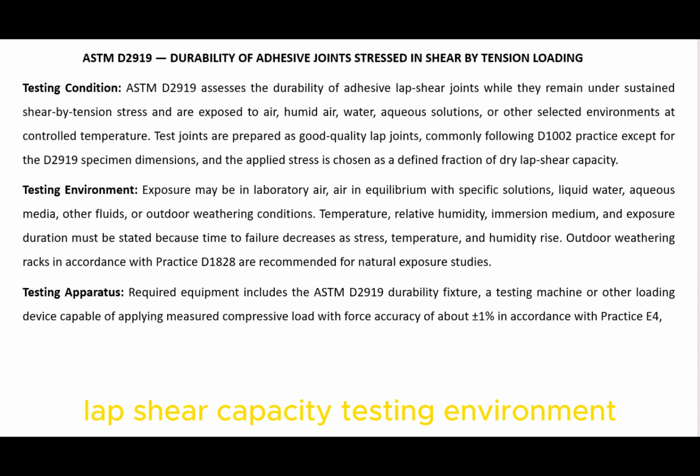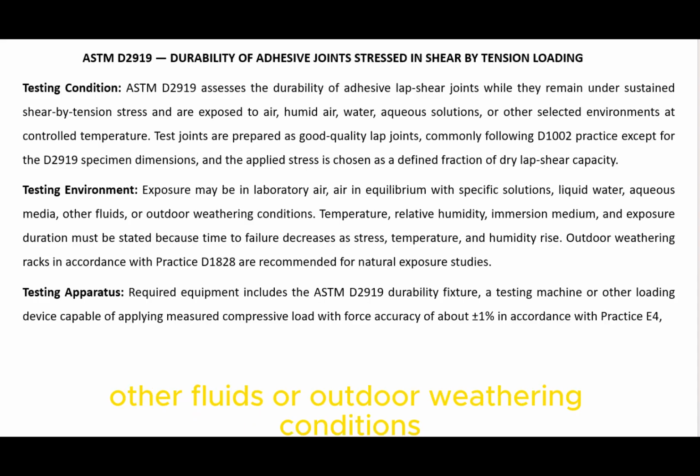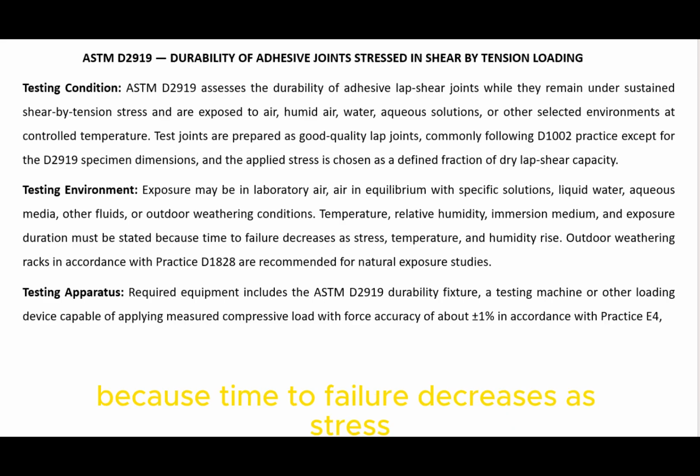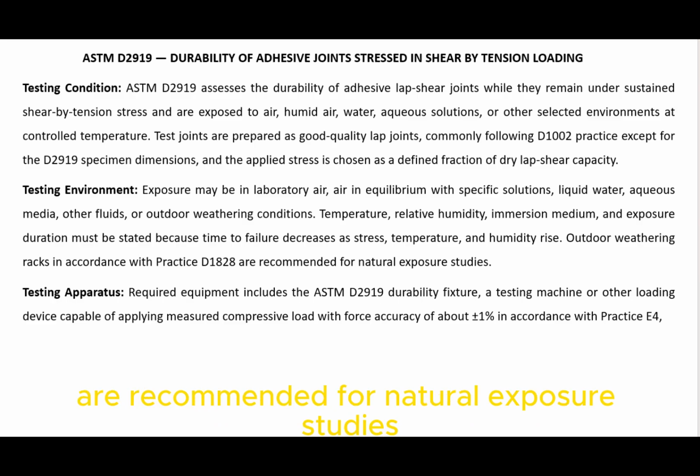Testing environment: exposure may be in laboratory air, air in equilibrium with specific solutions, liquid water, aqueous media, other fluids, or outdoor weathering conditions. Temperature, relative humidity, immersion medium, and exposure duration must be stated because time to failure decreases as stress, temperature, and humidity rise. Outdoor weathering racks in accordance with Practice D1828 are recommended for natural exposure studies.